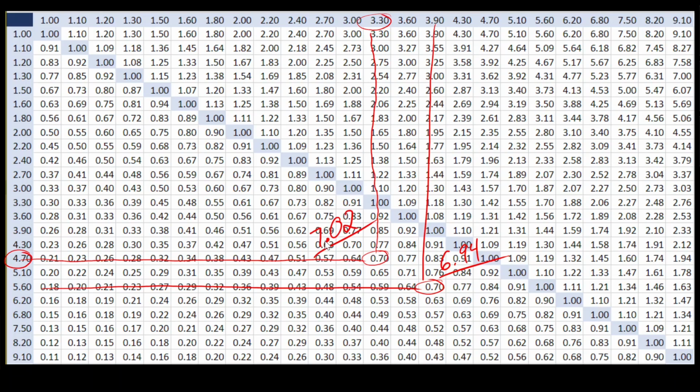By the way, sometimes it helps to do this the other way. Rather than saying 0.7, take the inverse of that and that's 1.43. And see if you can find that in the table. There's one here, which suggests a pairing of 3 and 4.3. So if we let our feedback resistor be 300K and our input resistor be 43K, that gives us a gain of 6.97. So far, it's looking like our first choice was the best.